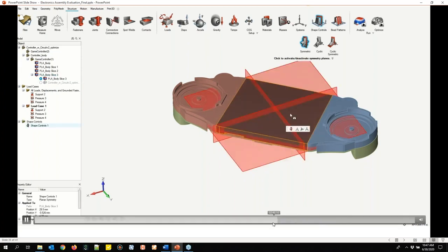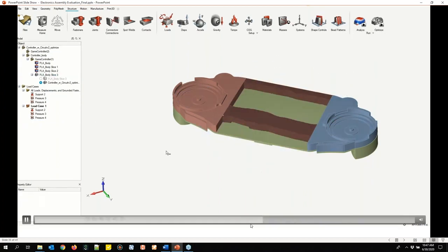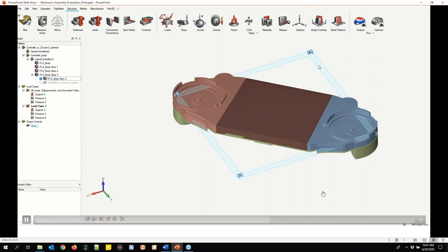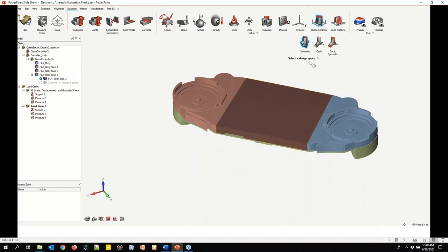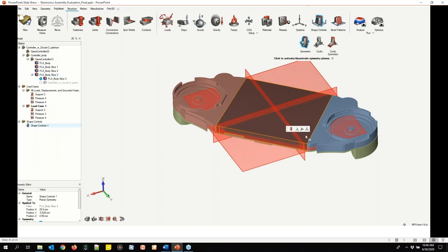And if I rewind back here a little bit, we can see that we get this stiffener concept. So this stiffener concept is not altogether useful because we already had this sort of back stiffener here, but it is telling us to place another stiffener here to help with our engineering objectives. So that seems like an interesting concept, but it's not interesting enough to me. So I'm going to change my optimization setup and take out that extrusion constraint.